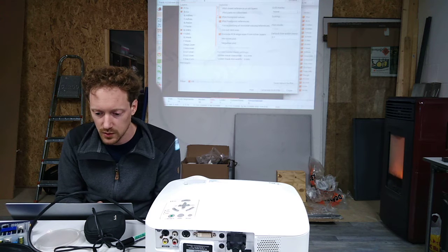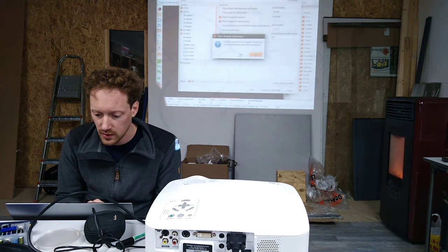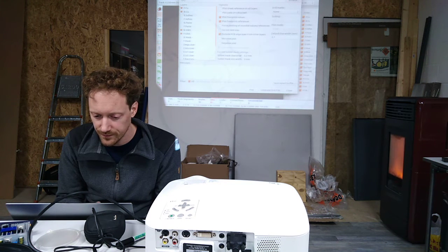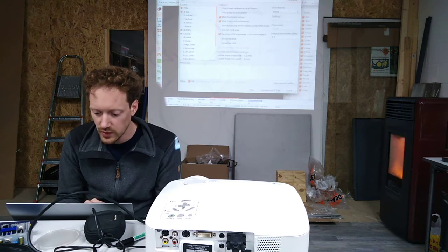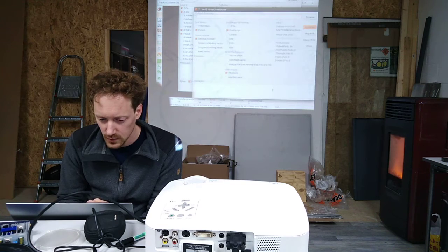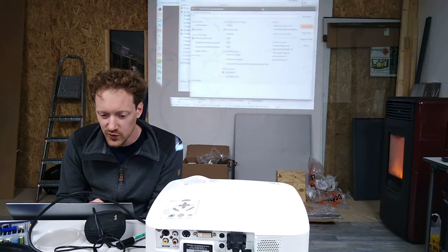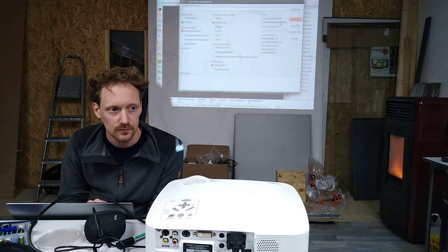So I'll put the directory here. And you can generate a drill file as well. It's also something we need, I think. Then we can use that in FlatCam to drill the holes.